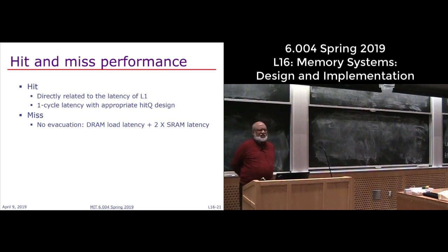The performance question, again, you will have to analyze. The hit case is the most important one, because we expect to be hitting all the time. And if you are hitting, then we want to get the response back, and you have to count the number of cycles. Did it take 1 cycle, 2 cycles, 3? Every cycle matters. On the other hand, once you get a miss, if you add a few extra cycles here and there, it doesn't matter, because the miss is going to take tens of cycles, maybe 100 cycles. So if you went from 100 to 102, it doesn't matter for performance so much.